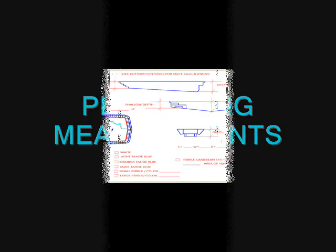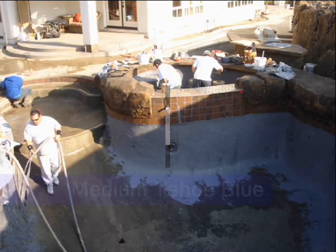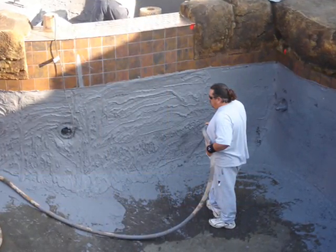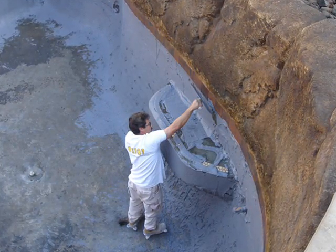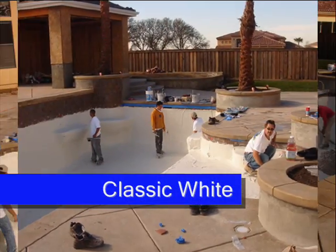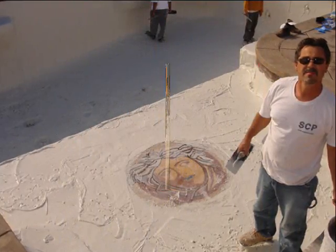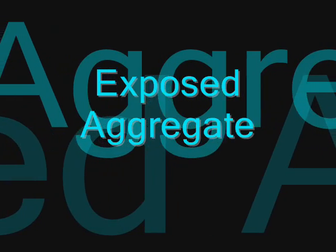When estimating the pool or spa's plastering areas, the gunite or shotcrete surface measurements can be applied, excluding the areas intended for tile, of course. The surface area square footage will be the basis for determining the estimated cost, together with the selection of the desired product. Plaster is generally a swimming pool industry terminology that refers to a refined form of white concrete mixed into a paste, which is then applied over the gunite or shotcrete shell.